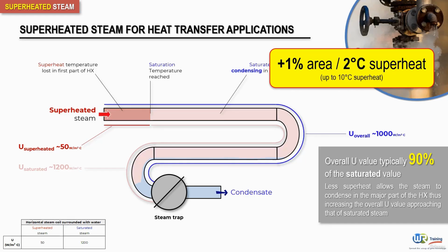We do not recommend that superheated steam above 10 degrees of superheat be used for heating purposes due to the probable disproportionate and uneconomic size of the heating surface, the propensity for fouling by dirt, and the possibility of product spoilage by the high and uneven superheat temperatures.